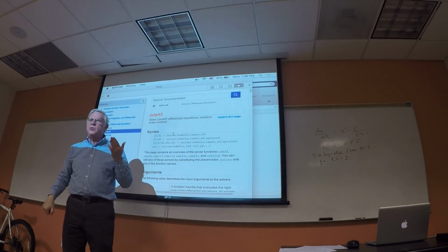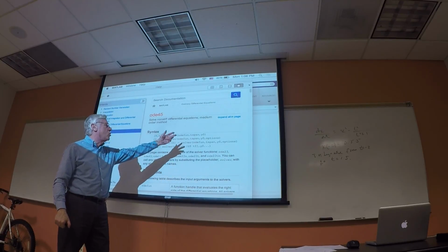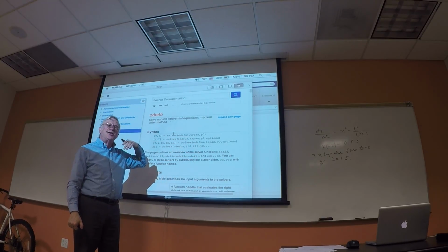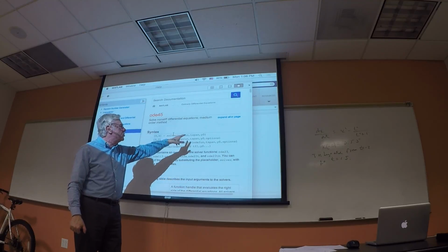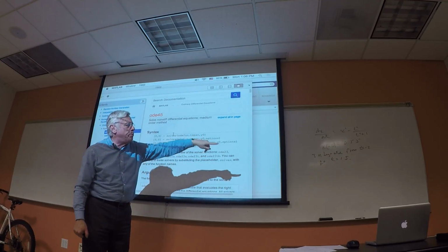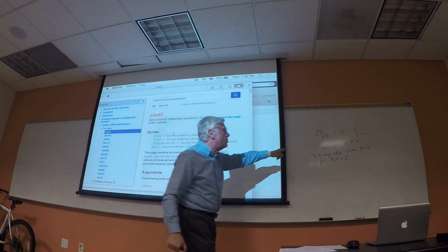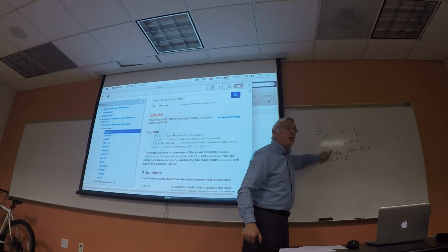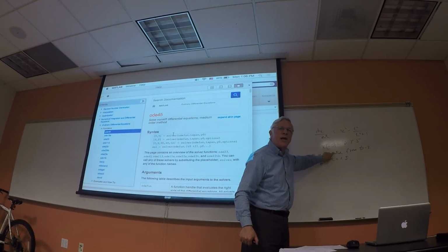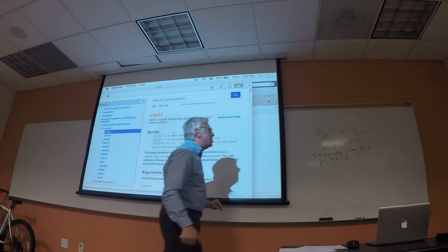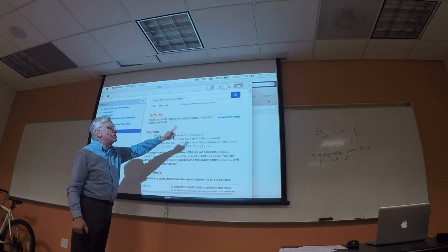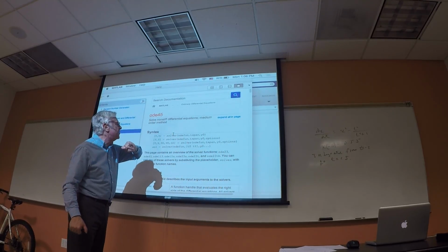It's a two-element vector. It's a very good name. Again, you can call it anything that you want, but it basically spans where the solution starts. So t span is a two-element vector. We'll put the first element equal to -2. Be very careful, not 0, because MATLAB will assume that the first element of t span is where you're starting, where your initial condition is. You have to be very, very careful about that. So the first element of t span will be -2. The second element is where we want to stop, in our case 15.